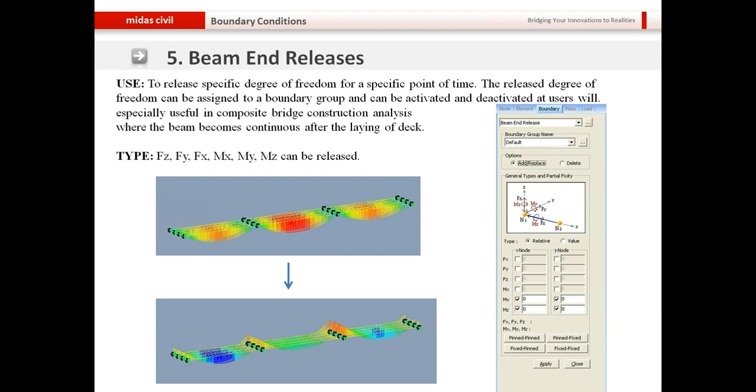In a precast I-girder bridge, let's say it's a 3-span continuous precast I-girder bridge. In stage 1, we install the girders of span 1. In stage 2, we install the girders of span 2. In stage 3, we install the girders of span 3. And in those stages, these 3 girders in 3 different spans are simply supported. But when the deck is cast on top of them and hardens, then they become continuous over the support.